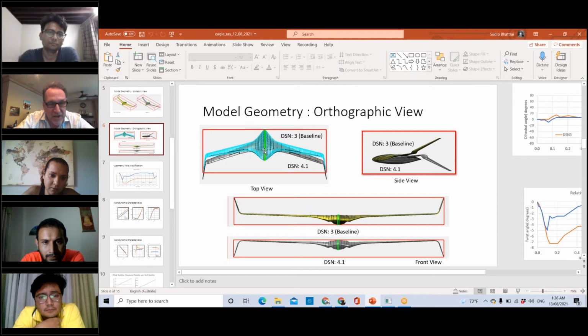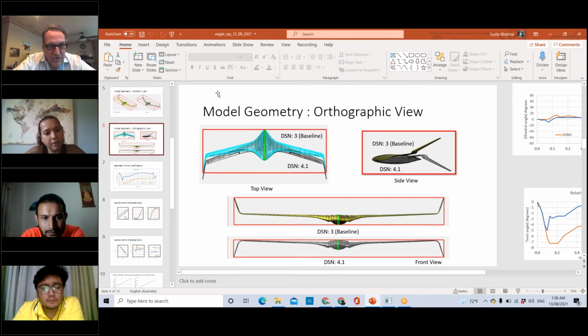Now, we could keep the sweep, and I know you guys have been largely preserving the planform, but my instincts would be that if we really like the extra sweep, we might need to shear the center body aft a little bit. Leave the wings where they are. Just imagine sliding the middle airfoil back to move the centroid of the volume closer to the target CG, so that we'll have a little less leading edge sweep, a little bit more of a trailing edge sweep, and then I think everything could line up nicely where the usable volume and the flyable CG are well aligned.